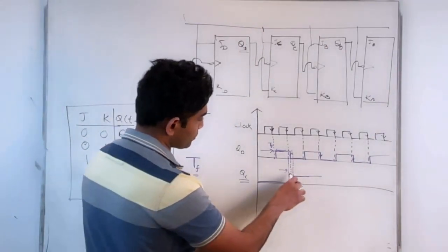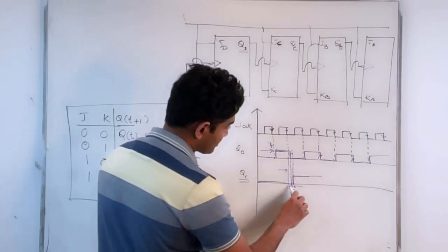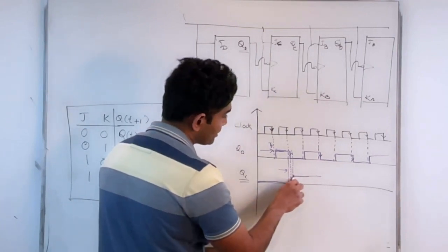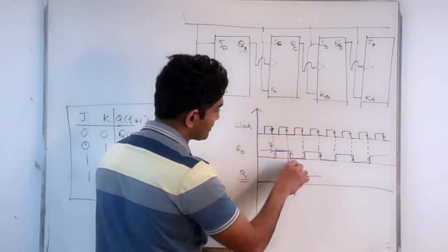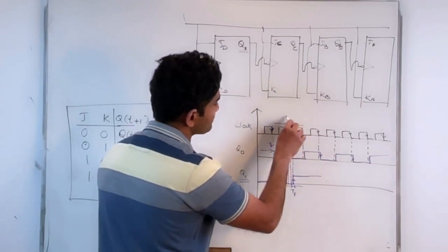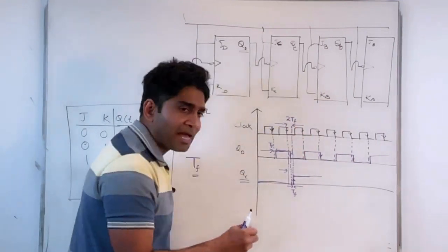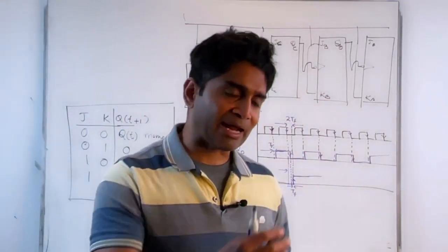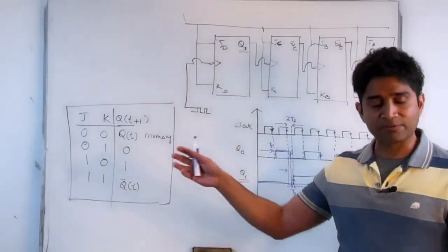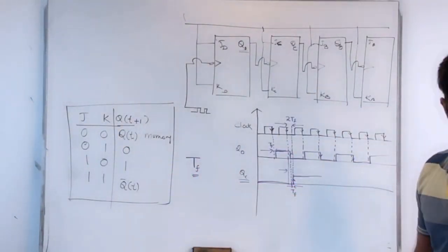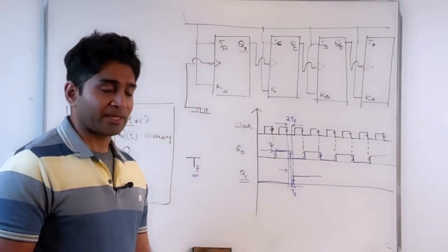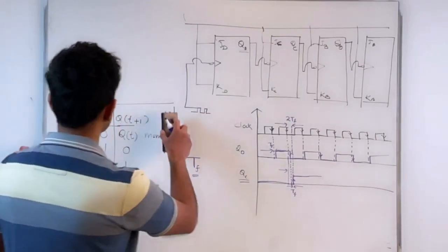All right, so that's TF. That means the timing delay of the switching of QC with respect to the master clock, if I extend this, became 2 times TF. In other words, as I'm adding new flip-flop stages, the timing delay for the nth flip-flop also increases n times. Now, what effect does that have on my count? Because ultimately, that's going to affect the count.